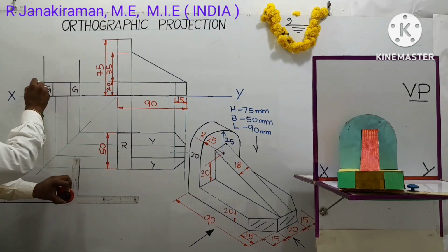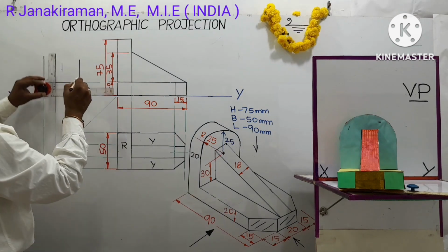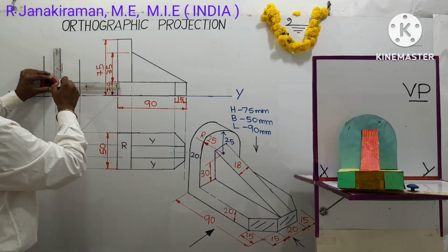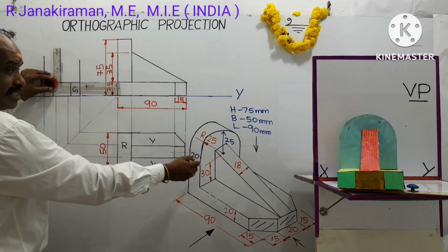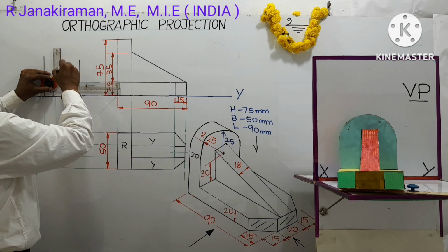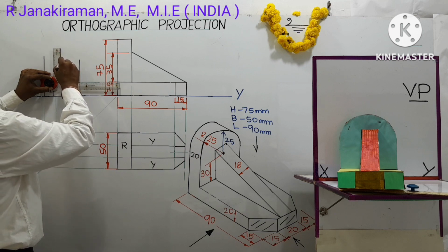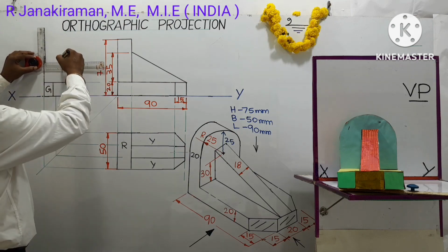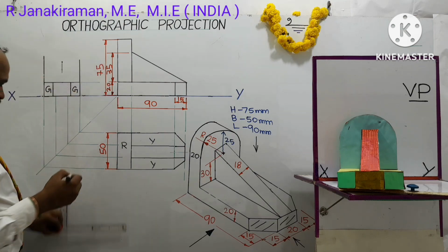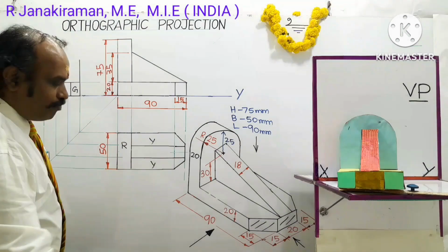This is top surface of the base. Okay, from here you measure from the base top surface, you mark 30 mm, that is 3 centimeter along this vertical scale of a drafter. There you locate one point. Okay, so this forms the center of the semicircle. Next, take your compass.